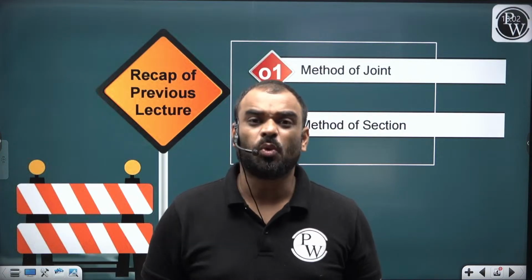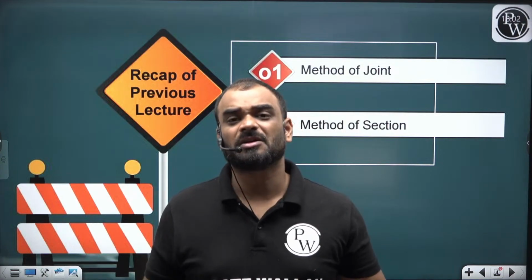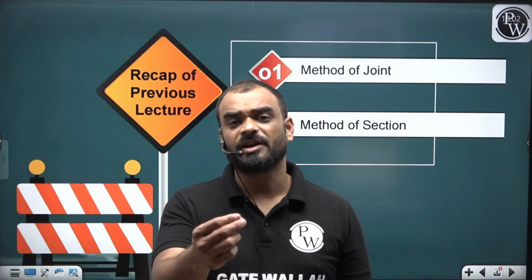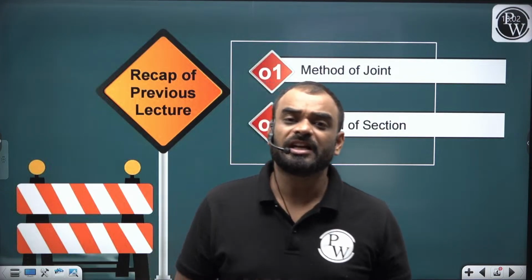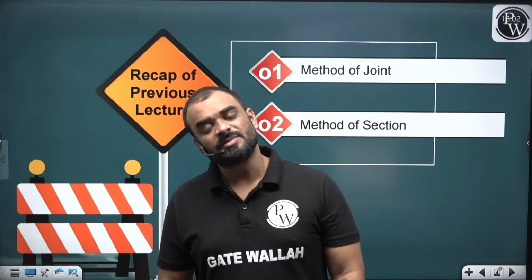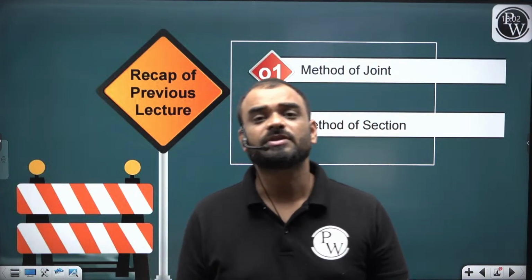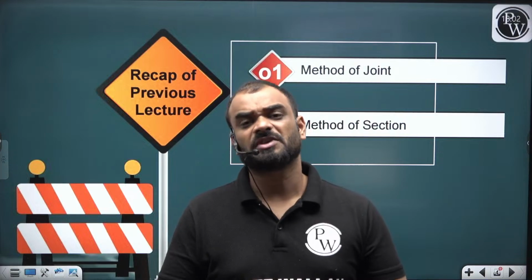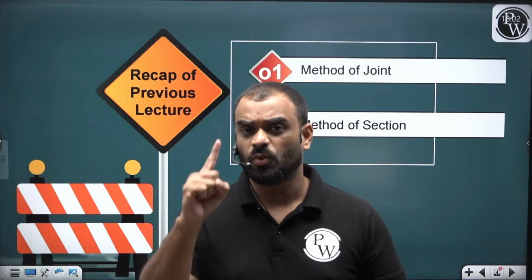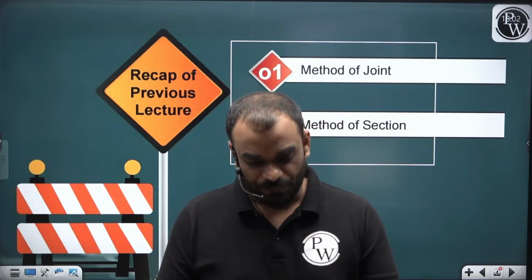Why? Because whatever members you have, the forces in these members are concurrent at the particular joint, and if they are concurrent at a particular joint, then you are not able to write summation Mz = 0 by using these force members or truss members, right? So that's why, guys, we have only two joint equilibrium equations: summation Fx = 0 and summation Fy = 0.